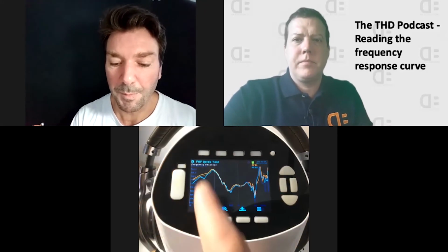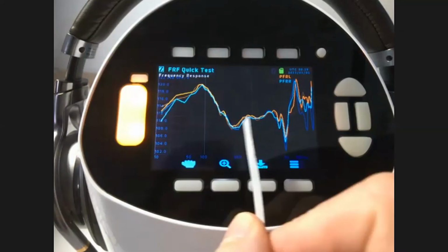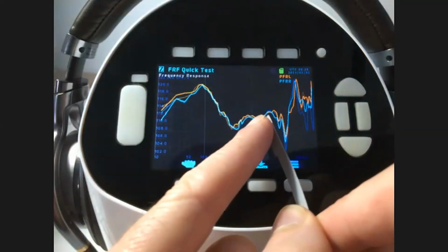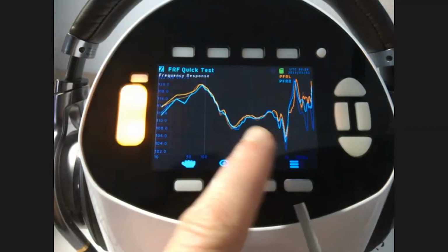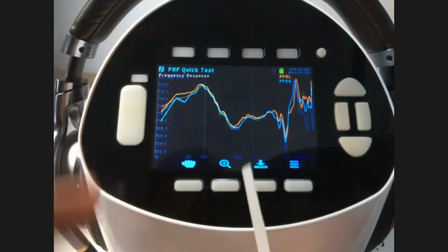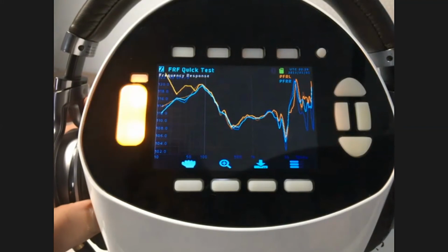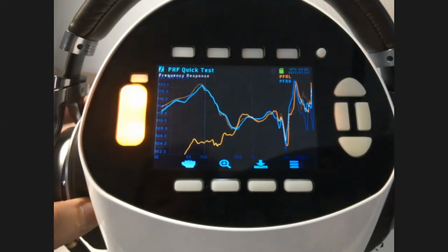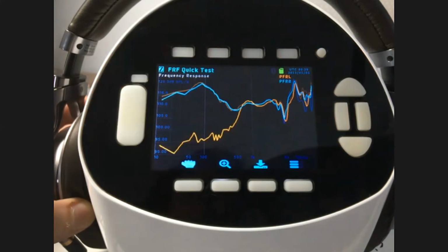So that's the rear chamber porting effect. If you made that port larger, that notch would go up in frequency. But it will get to a point where it will stop having any effect. I'm going to open this up, and we can see we're bleeding off energy.